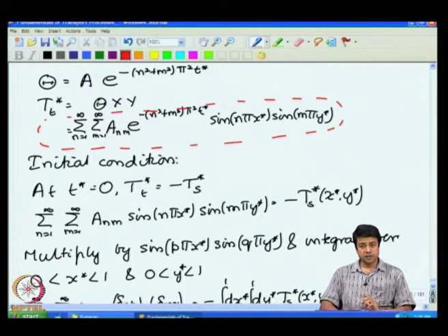There was an inhomogeneous direction, the x direction, where the temperature on the left face was not 0, the temperature on the right face was not 0 either. For that inhomogeneous direction, we managed to obtain a solution basically in the form of exponentials, one exponentially decreasing, the other exponentially increasing.